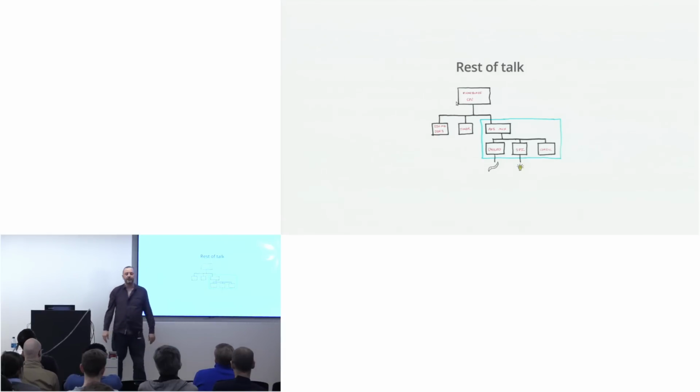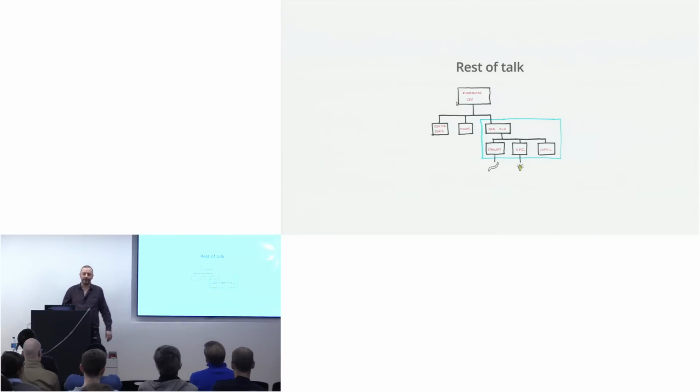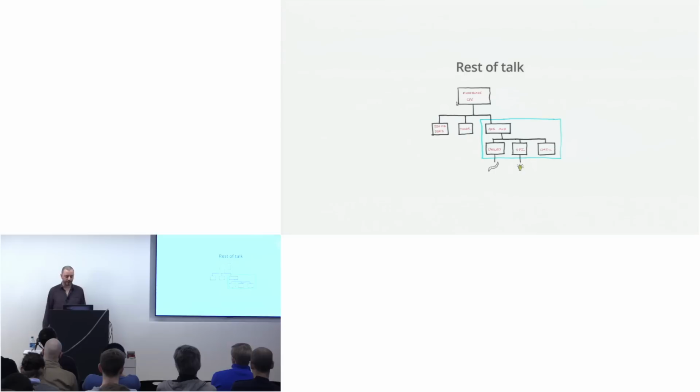There's a SPI core. SPIs are like a standard communications interface between low bandwidth hardware. And that's attached to a light sensor, which is connected to the board here. And finally, I stuck a little Cordic core. Now, Cordic is like a clever math algorithm for hardware that calculates things like sine and cosine and hyperbolic functions and so on. But it just does it with adds and shifts.